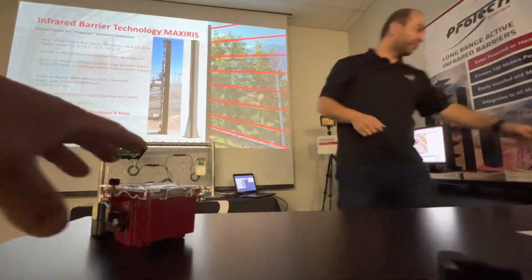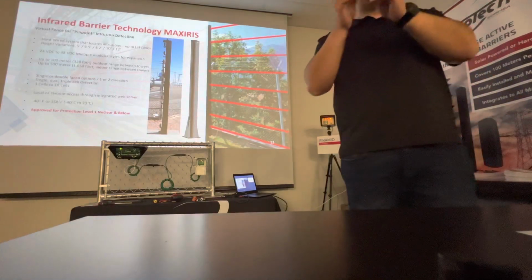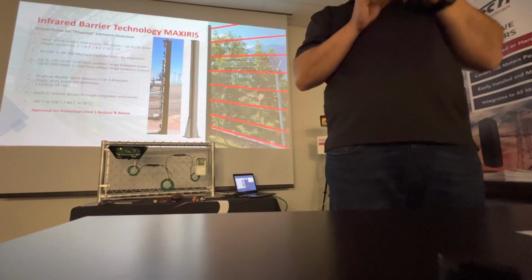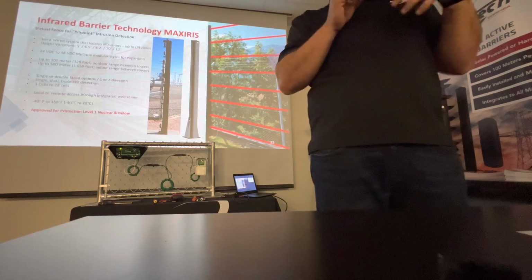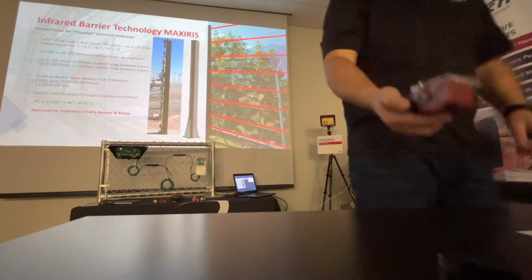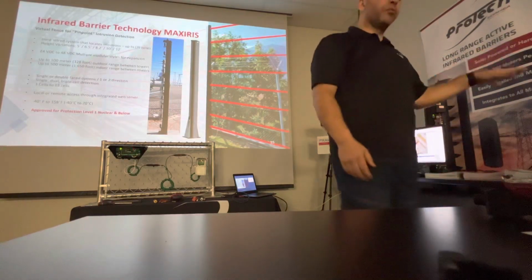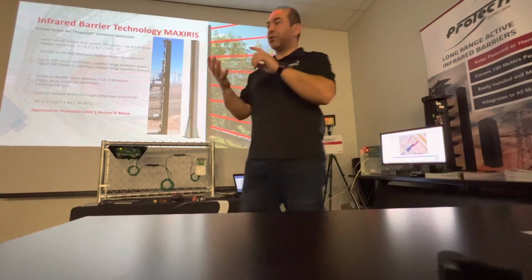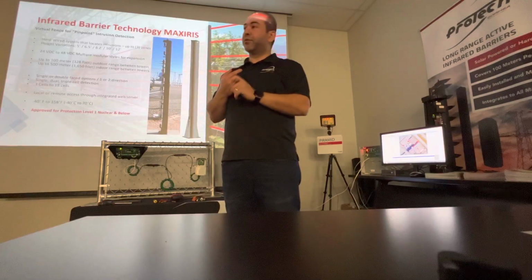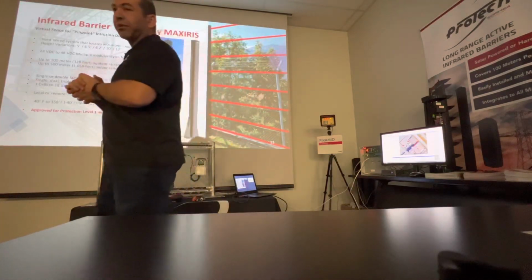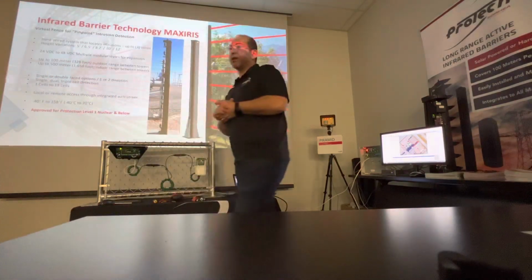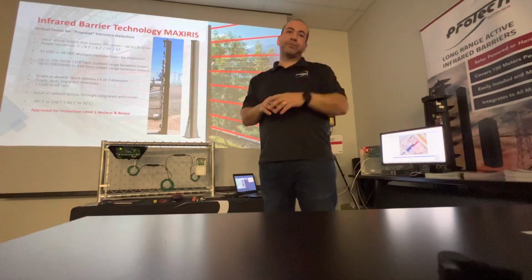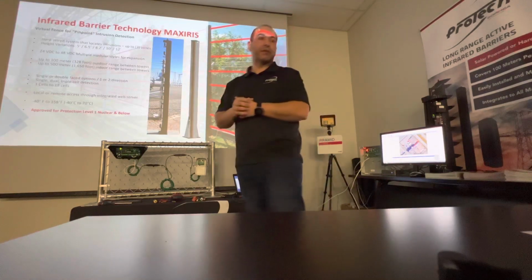If you see the cell here, during winter conditions, this green part is a resistor, so this is like a heater, just to keep the infrared cells warm, to not make any condensation during the winter. So this is why it's not solar based. It comes with different power versions, transformer inside, so 24 volt DC, 48 volt DC. So this is usually what I recommend, and there is a 12 volt DC, but I recommend the 24 volt DC for the heater. It's more powerful, it's more amperes. Right? So.